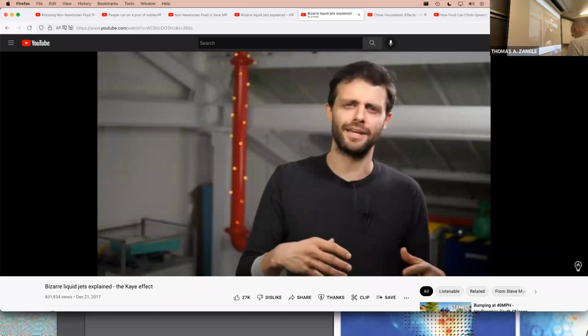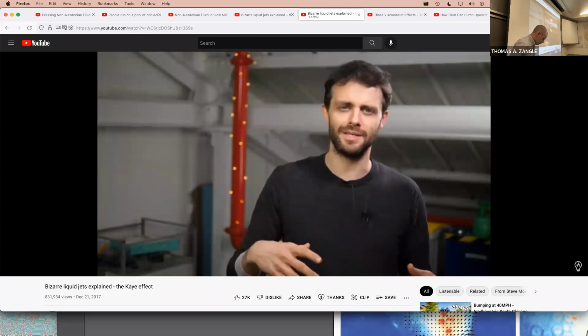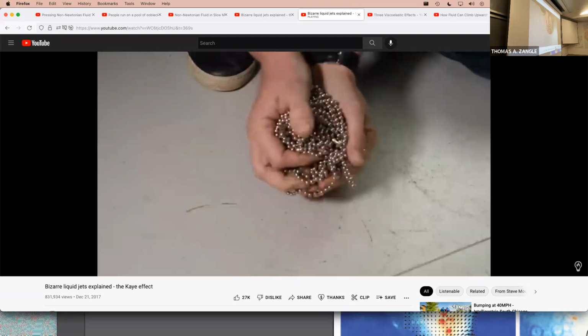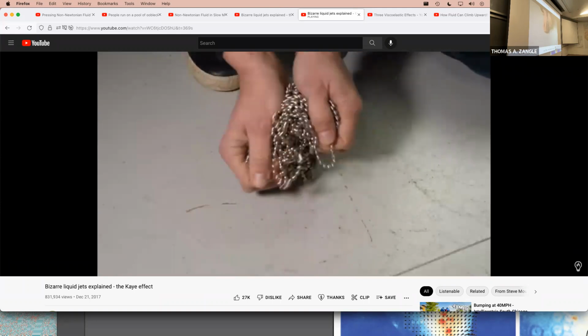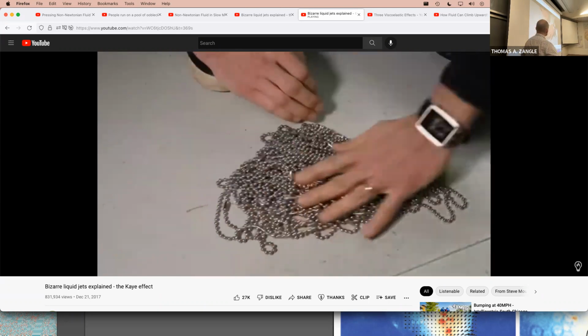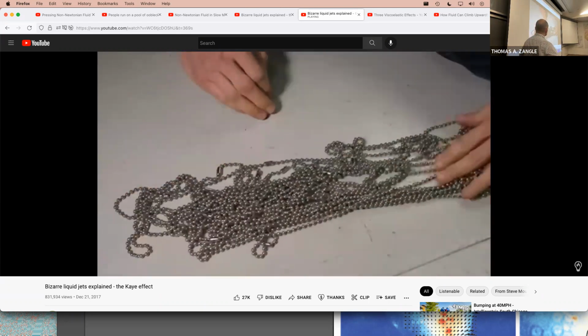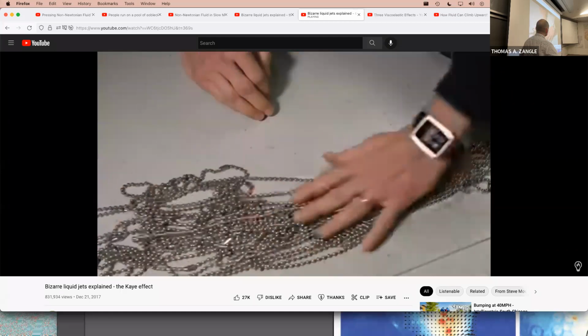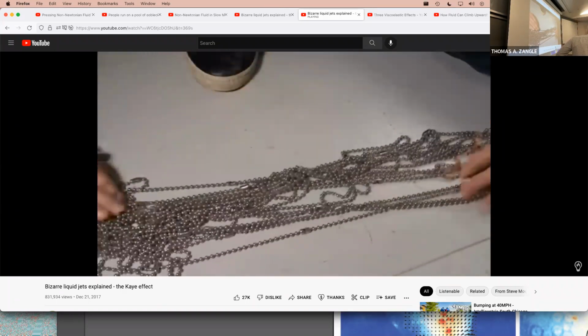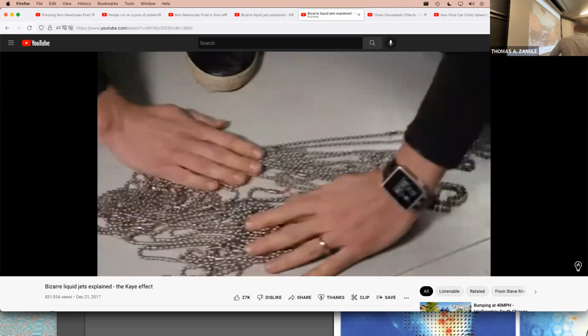How do they shear thin? Well, they're polymers, which means they're really long chain molecules. They're like these chains of beads here. And normally they're all tangled up with each other. They can't move very easily. And so they add viscosity, they add thickness. But if you apply a shear force like this, the molecules spread out, they smear out, and they line up. And then like that, they can more easily flow over each other. So the viscosity goes down, they shear thin. There's still a part of the explanation missing, but we're going to leave it there for now.